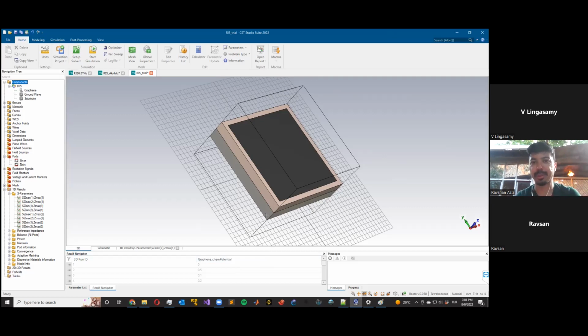See, you assume that it's going to be broadside incidence, right? But when you have offset incidence, what will happen? At that point, that particular phase is going to change, right? The reflective amplitude and the phase would be changed, hugely. But the thing is, we can have some kind of buffer, plus minus 45 or something like that. We can evaluate how much change we are getting. We will not get much change if it is plus minus 45 degrees. But if you go beyond that, then you will get some difference in the radiation pattern.